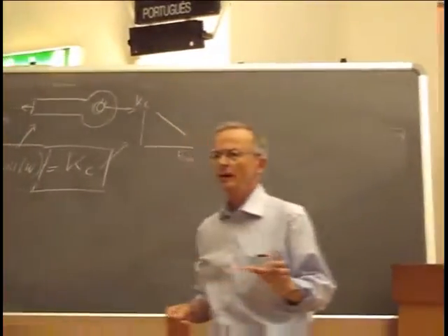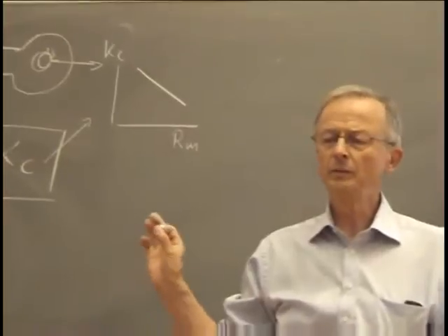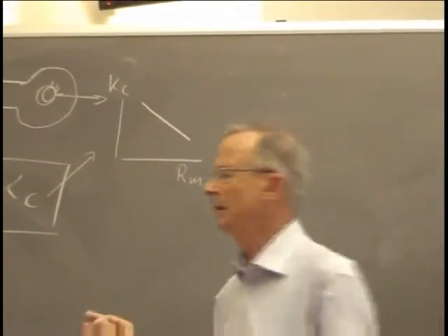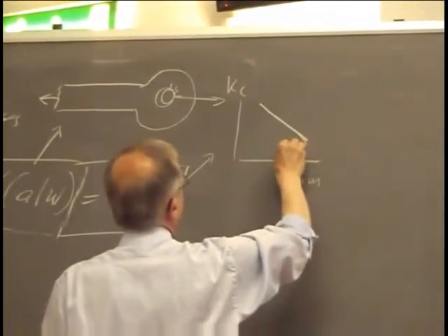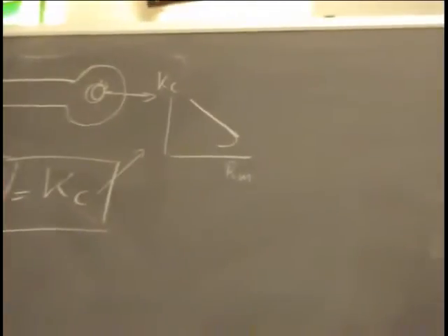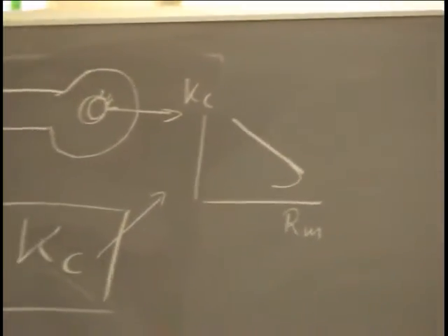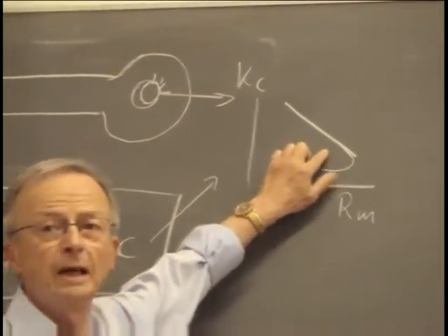And sometimes when you have age-hardened materials, the correlation between toughness and strength can be unequivocal, because you can get a curve like this here. And this is due to overaging. What happens? When you overage, you soften the material, so you would expect that the toughness goes down again.